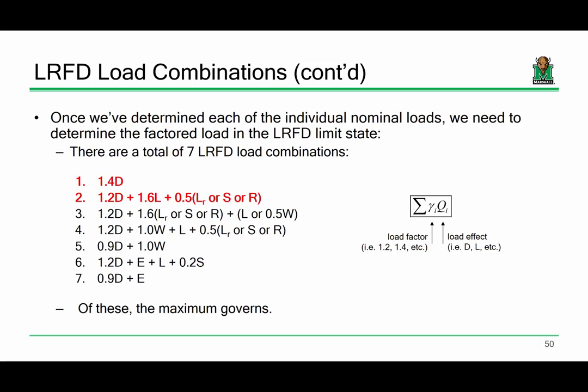That's a good question. So the one that's a little unique is L sub R. It's a live load that is just applied to the roof. Usually you're considering live roof loads either during construction, or if for some reason there's personnel or occupancy on the roof, but it's essentially another live load. So that's a good question. It's not really handled drastically differently though. It's all basically the same.